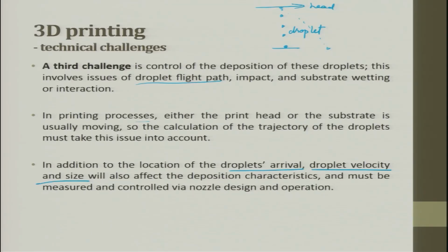At the exit they have a piezo crystal. The opening of the piezo crystal happens so fast, and the droplets are formed and allowed to drop. If the droplet which is formed is too small, then in flight, when the binder head is moving, this droplet will just ooze out and fly in the air. So, you have to be very careful. This is a huge challenge.